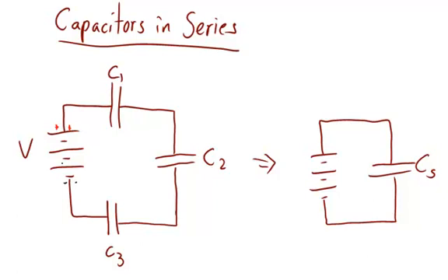How much charge migrates? Well, let's take a look and see how this works. On capacitor C1, when charge plus Q appears on the left-hand plate, then there's an equivalent amount of charge minus Q that appears on the right-hand plate. Where did that charge come from? Well, in the circuit, there's only one place it could have come from, and that was from capacitor C2.